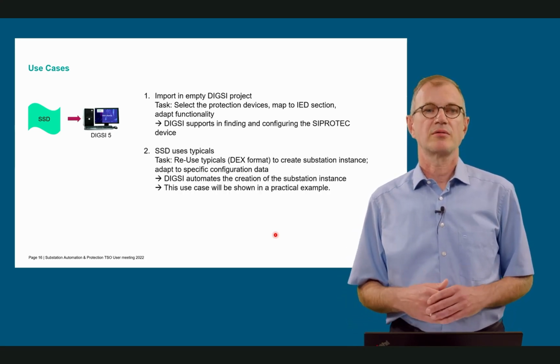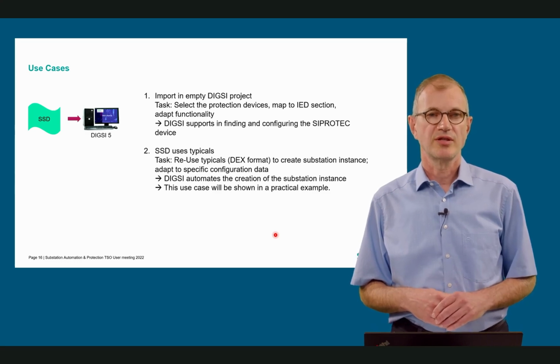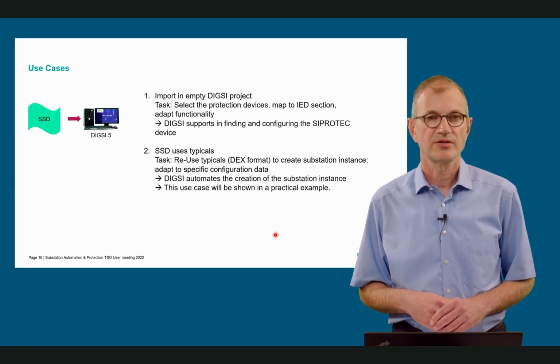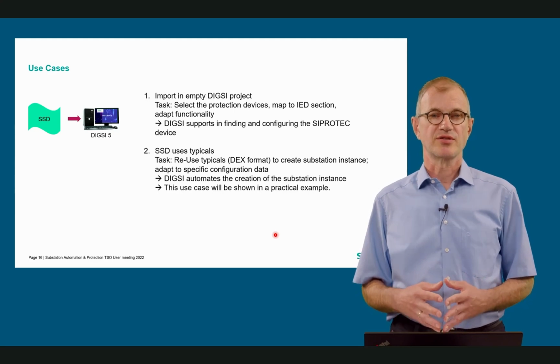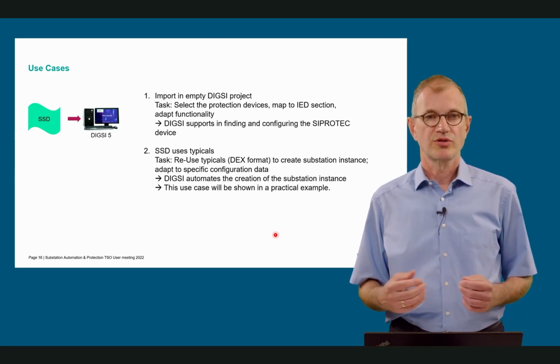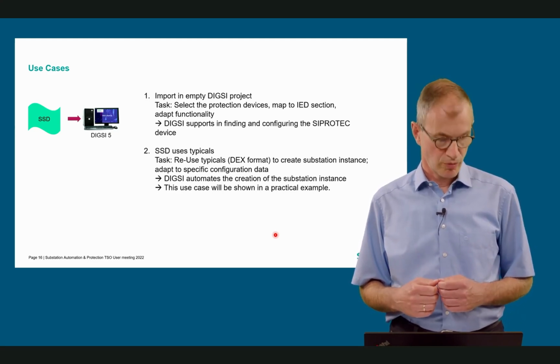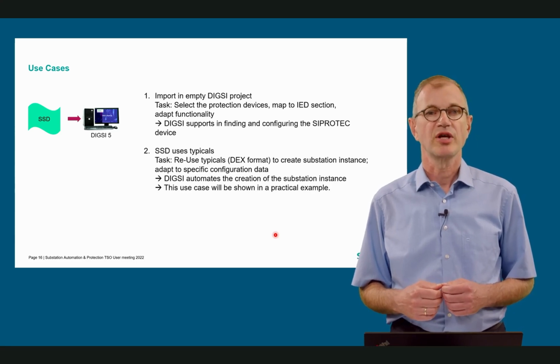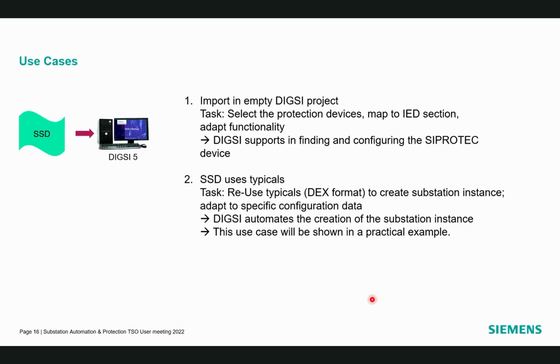The second use case is that the SSD uses available typicals. Then the task of DIGSI is simpler. It's to reuse the typicals, which should be available in the DEX format, to create this substation instance. You can also start with an empty DIGSI project, but DIGSI then automates the creation of this substation instance, and we will look at this use case in our practical example following soon.